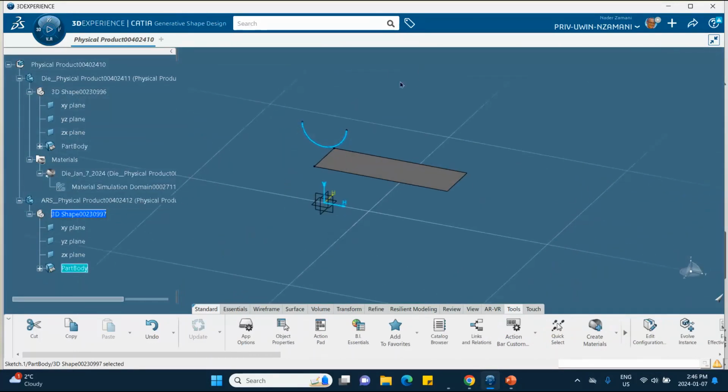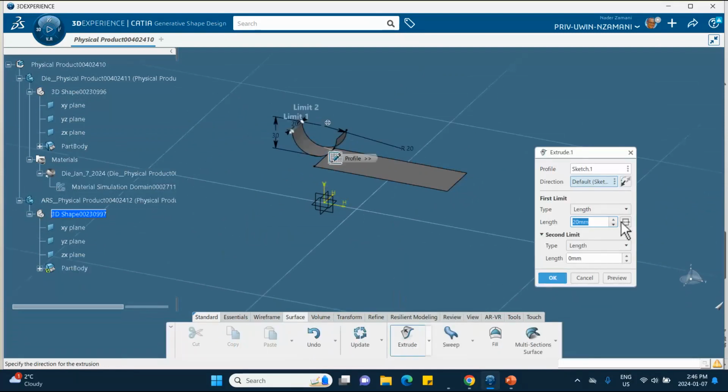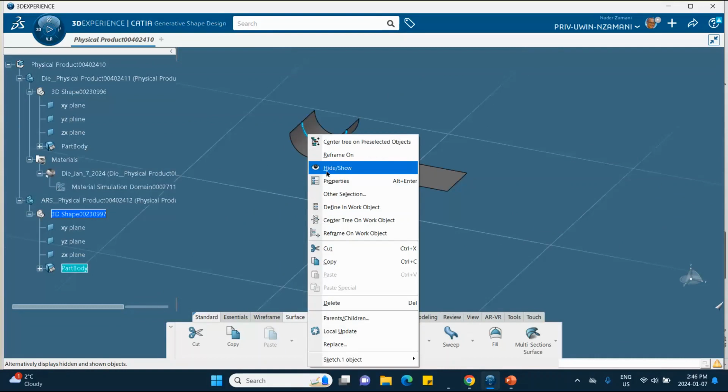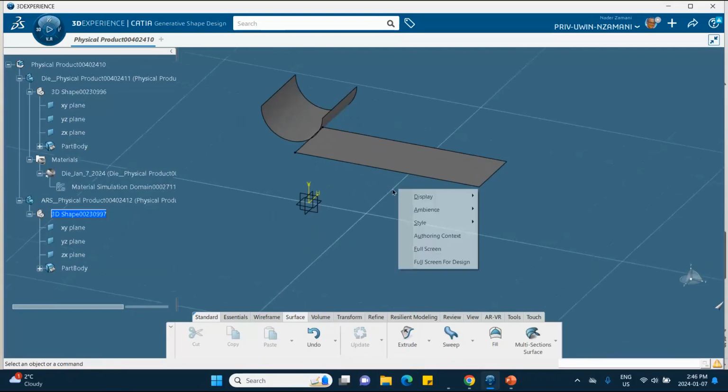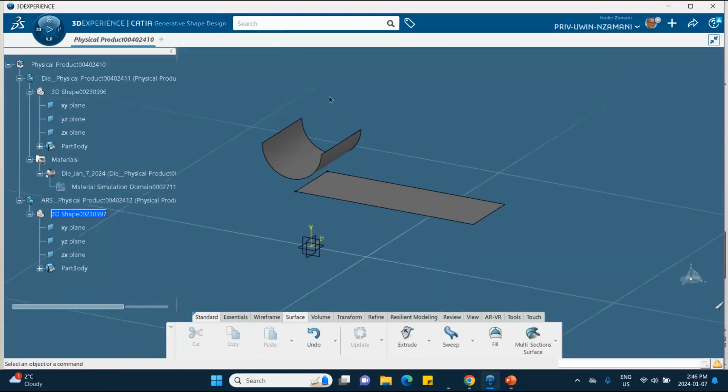Now this I'm going to extrude in each direction by 25 millimeters. So we go to surface, under extrude. Here's the symmetry. See that? See this icon? Symmetric. 25 in each direction. It gives you a total width of 50. There we are. And incidentally, I can hide this sketch. So there is our geometry.